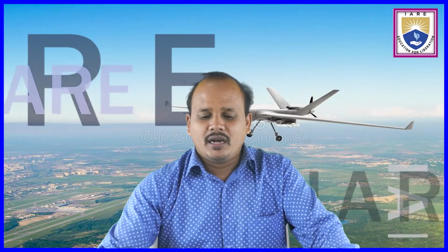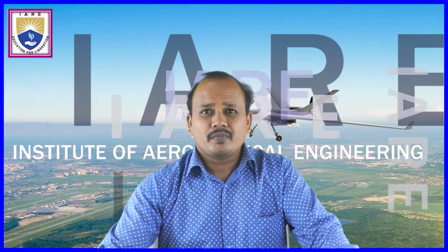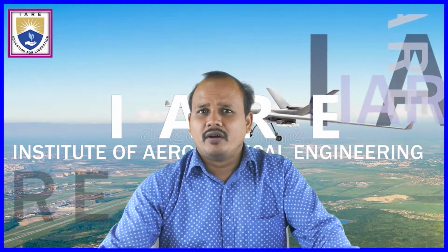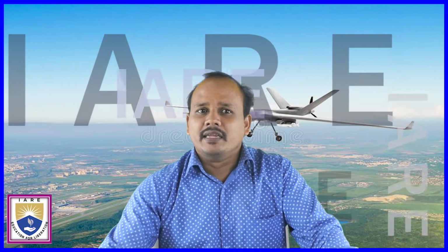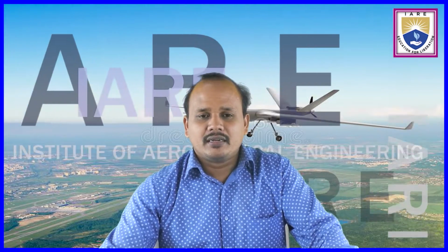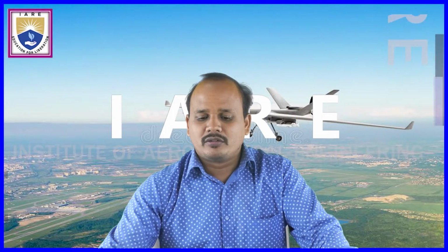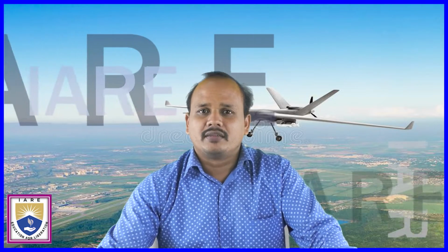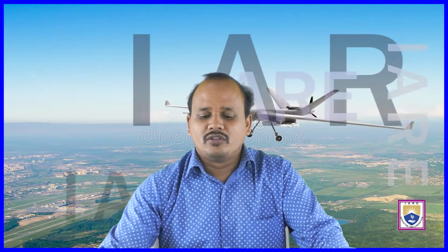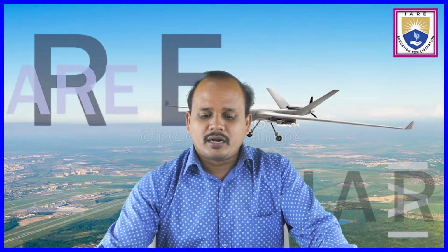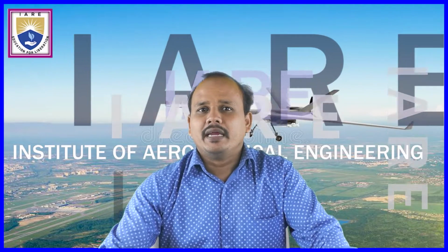After that, we discussed the operational modes of your supersonic intake. That is, instead of flying your aircraft at the design Mach number, if we fly at a Mach number less than the design Mach number and greater than the design Mach number, what is happening in that supersonic intake? That's what we call the operational modes of a supersonic intake, and we have seen the subcritical, critical, as well as supercritical modes of a supersonic intake.